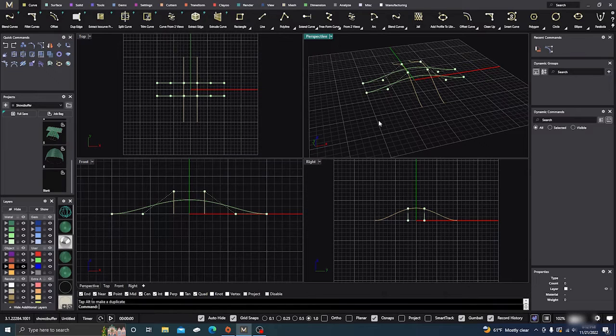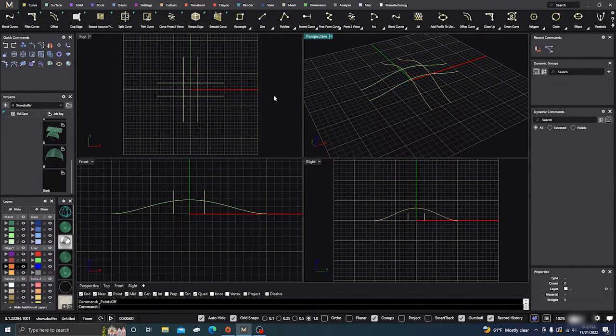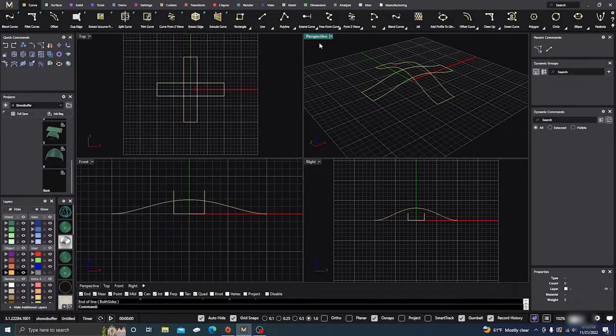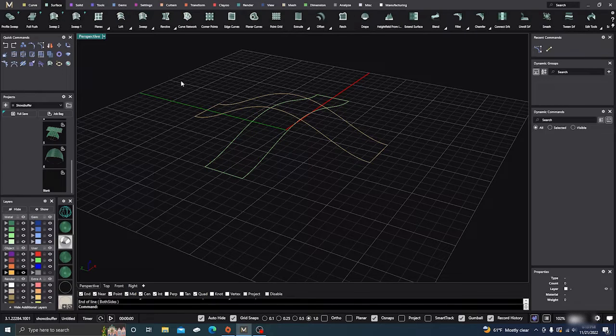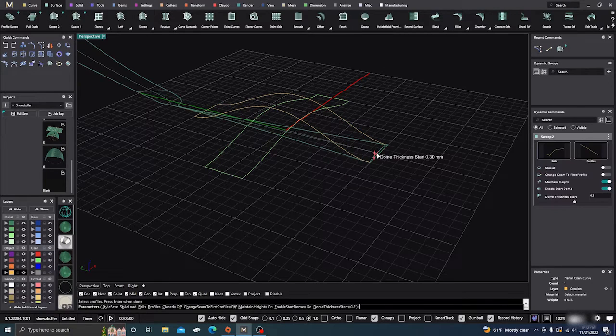We'll hit F11, get rid of our points, and then from here what we'll do is we'll go ahead and take that curve or a line curve, and we want to just close these off for right now. And then I'll do another one, but we'll keep everything in the same colors so it will be easier to tell what's what. And we'll go in here, and now what we'll do is we'll just go do a surface, surface 2, 1, 2, 3, 4, enter.